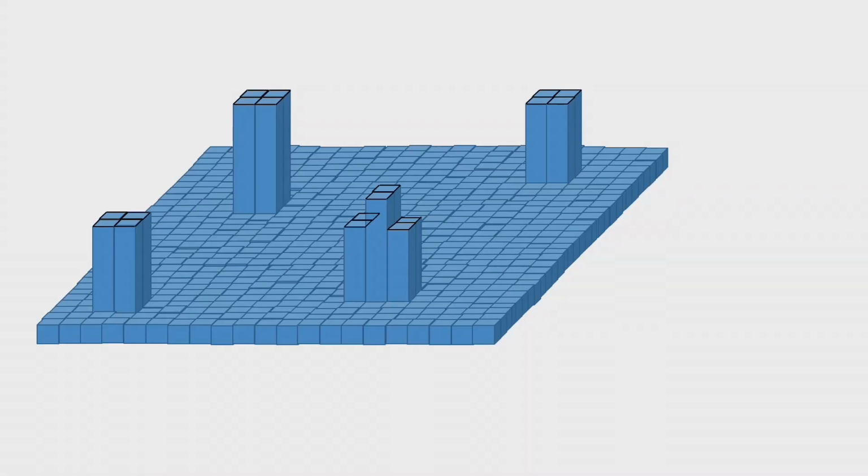So, we have generated the 3D coordinates of tie points. However, at each and every point of the image, I have not calculated the 3D coordinates. So, using those points for which I have calculated 3D coordinates, I will do the interpolation, and the interpolation creates this kind of grid. This grid system, where each value on the xy pixel indicates height, is called a DEM, and that is the first product of photogrammetry.